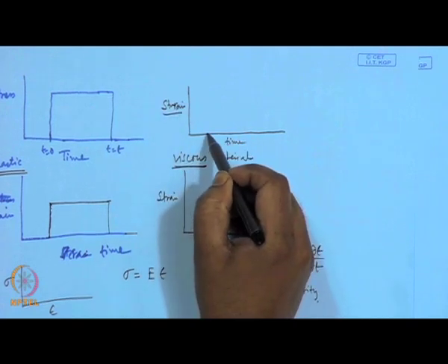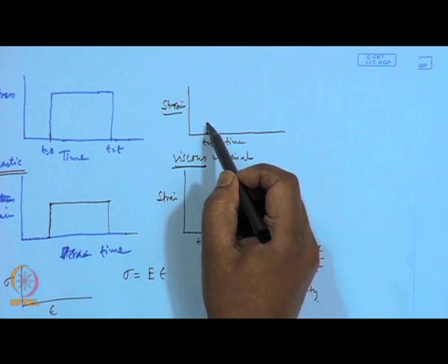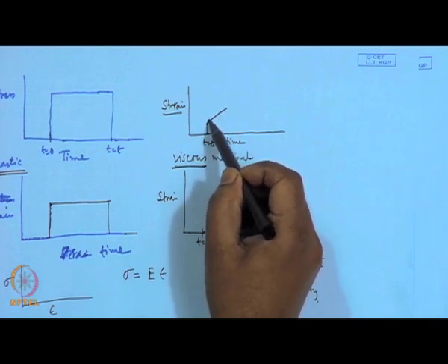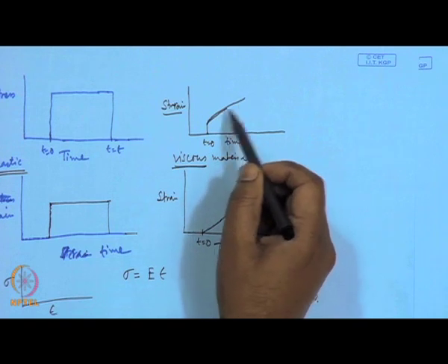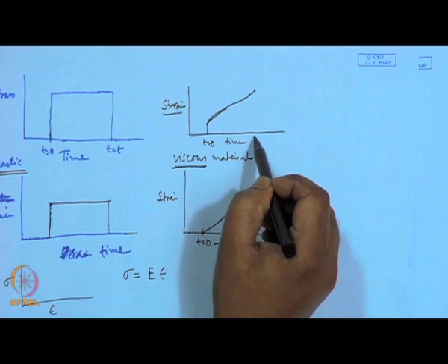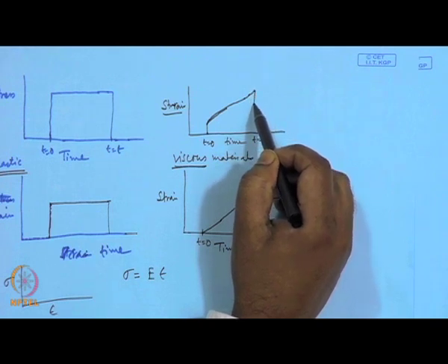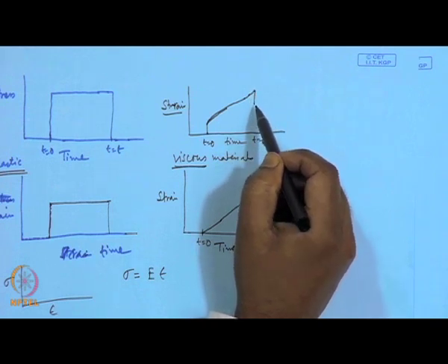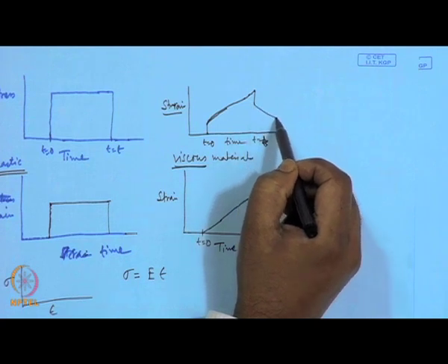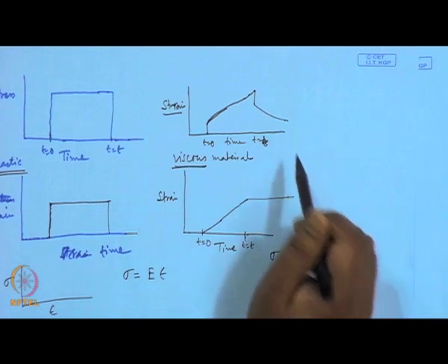So, at the time you apply the stress, it will strain to some extent and then keep on deforming as long as the load is present, and when the load is removed at t equal to t, it will recover some part and then stay somewhere.